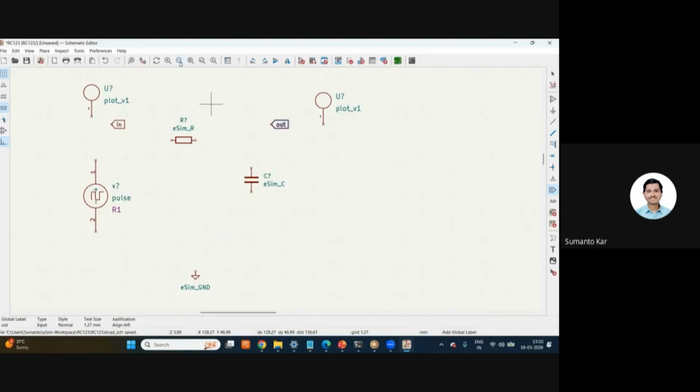In SPICE, these are like designators. So C means capacitor, R means resistor. Similarly, U is used for predefined components which are understood by SPICE or eSim in general. For example, integrated circuits are generally sub-circuits, but there are some predefined components like digital blocks and so on. For that, U is used. While doing eSim, U is useful.